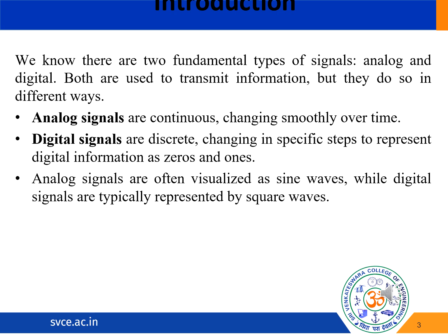And considering the specification of analog switches, whenever you select an analog switch, we have to consider some specifications. For example, first we can consider on resistance. So nothing to confuse with on resistance, but on resistance is nothing but the resistance between the input and output terminals when the switch is on. Okay, so on resistance you have to understand as the resistance between the input and output terminals, right? So when the switch is on, you have to focus on that. So typically in the range of a few hundred ohms.